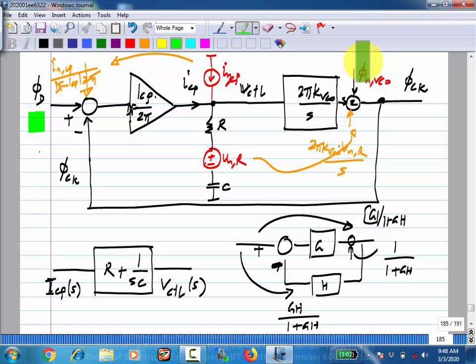I mean, there are sort of two views of negative feedback you can take. The two are useful in different situations. One is the following. You have a target, and then you look at the actual output, and you measure the error between the actual output and the desired output, and you go on adjusting the output. This is like following some target. The other is cancellation. I mean, this is also like following, but in the opposite way.